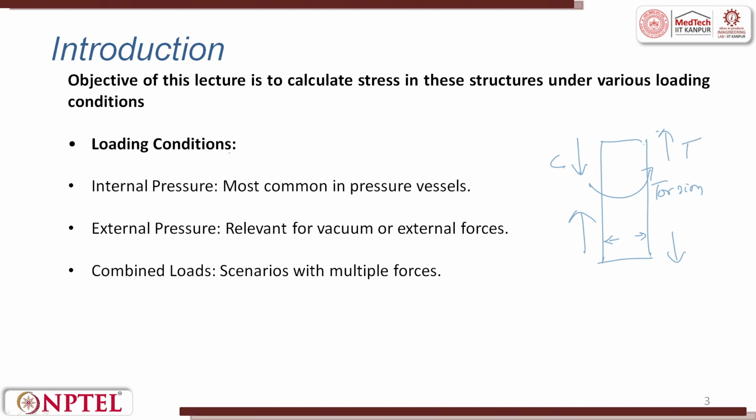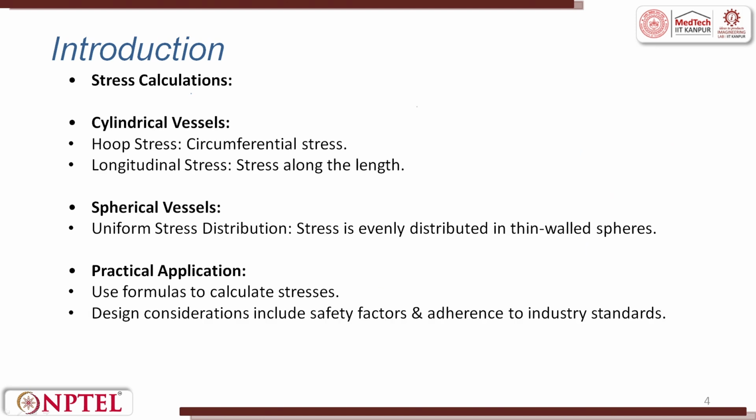So, the loading conditions can be internal pressure, most common in pressure vessels. Then you can have external pressure, relevant for vacuum, or external forces, or you can have combination scenarios with multiple forces. You can have varying loading conditions. Stress calculations: we will see in a cylindrical vessel and in a spherical vessel what are all the stresses which are going to happen.